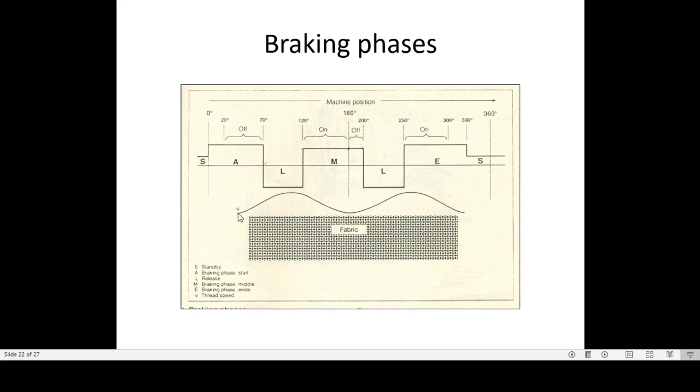So the left hand rapier grips the weft. The velocity of the rapier increases up to here, and when it comes to the center the speed reduces. Here from the left hand rapier, the right hand rapier grips the weft. When it takes the weft backward, the rapier speed increases, obviously the speed of the weft increases, and when it reaches the right hand housing, the speed reduces. So the velocity of the weft is not the same, it is increasing, decreasing, increasing, decreasing.